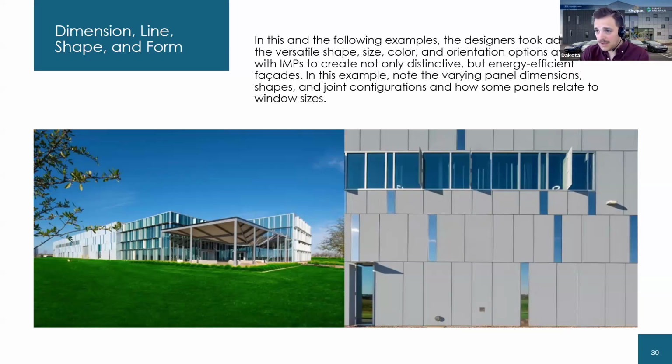Single skin is the second flavor. Think of corrugated or ribbed metal profiles, commonly used in industrial or utilitarian buildings. They're often lightweight, cost effective, very versatile, and people love perforating them. Plate is the third one. It's still an ACM look, but this is a non-combustible variant. It's essentially thicker. The reason we want it thicker is that we can still achieve nice, fun geometries, but we can also get good performance out of longer spans because it's a thicker metal, meaning it doesn't oil can. Oil canning is the phenomenon of metal getting hot and getting wavy. We don't like that, so sometimes we use plate. Insulated metal panels are the final flavor that we're going to be talking about.